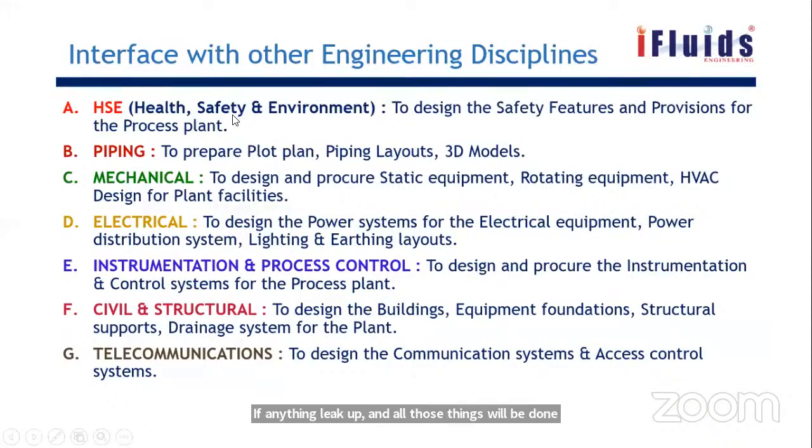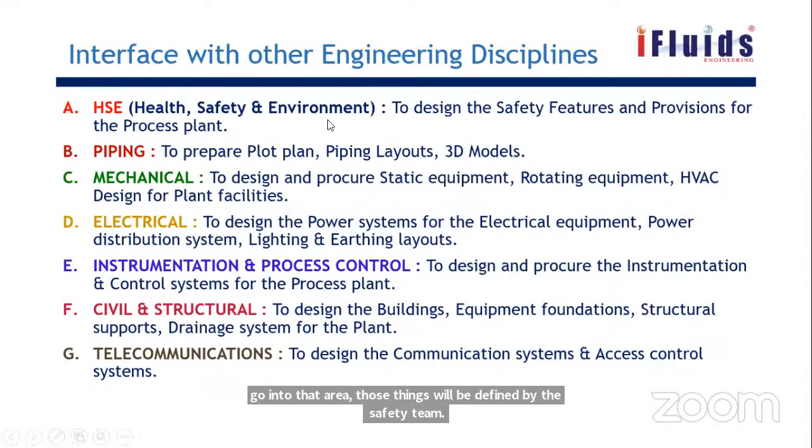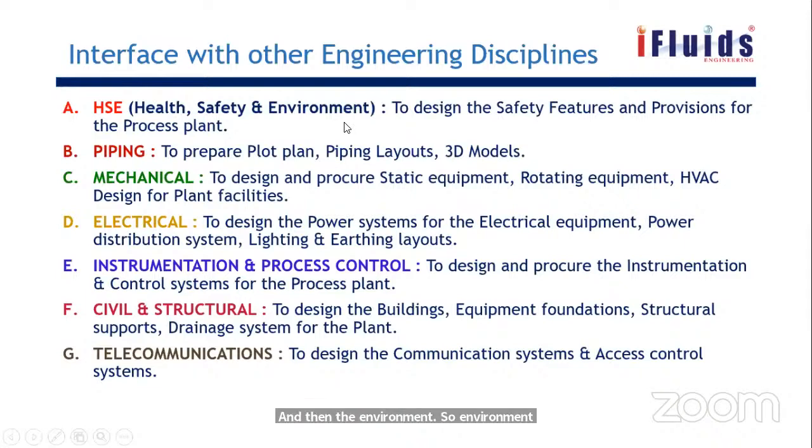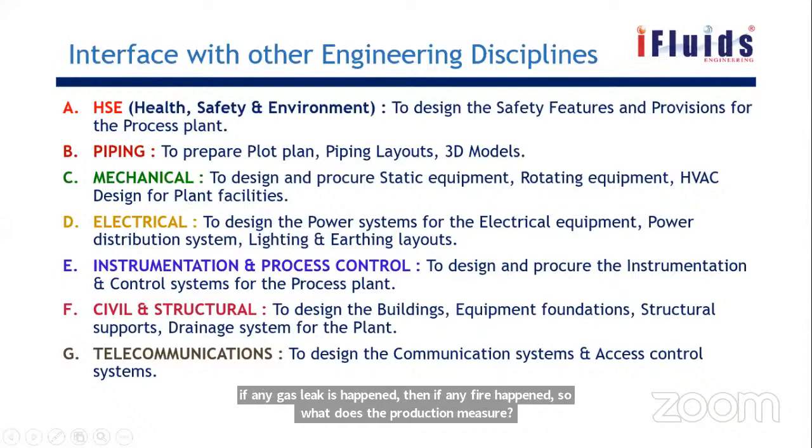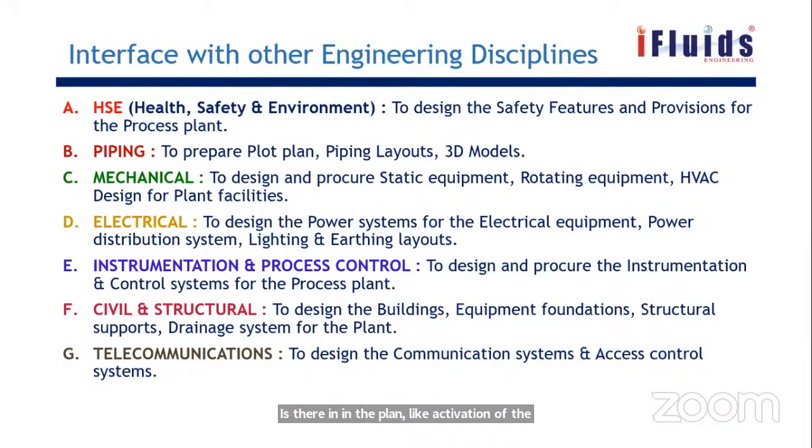And then safety, in the sense that if the noise is high, we need to block our ears with earplugs, and similarly in a high heat area, we need to wear a special suit to go into that area. Those things will be defined by the safety team. And then the environment. If any gas leak or fire happens, what protection measures are there in the plant, like activation of the detectors and the sprinkler system, the fire protection system. Those will be covered by the HSE team.